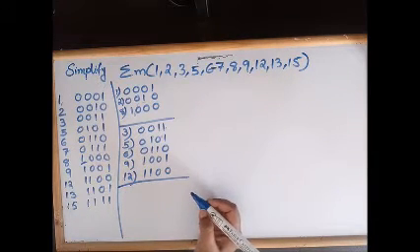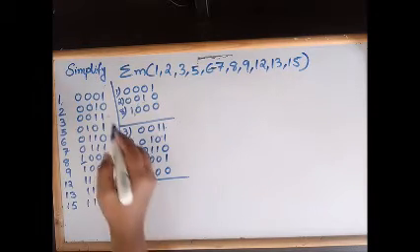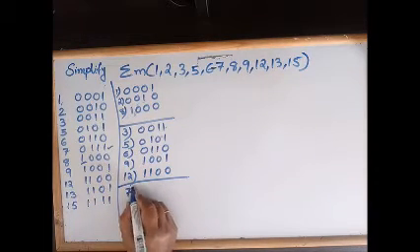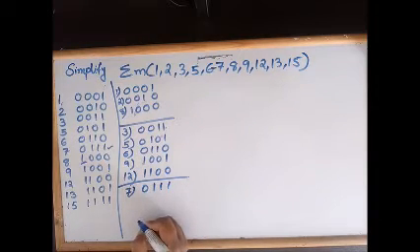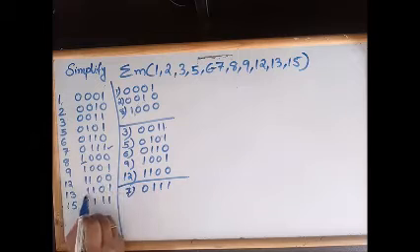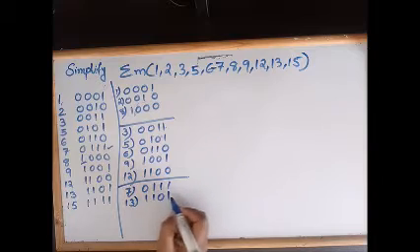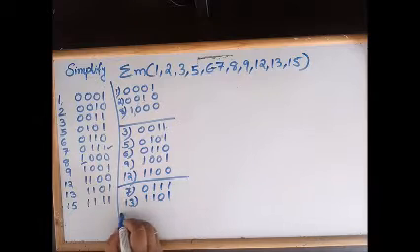Now we can generate the third group. This third group means the group of min terms which is having 3 ones in that binary representation. Okay, so consider the 3 one bits. When you consider the 7, it is having 3 ones in the binary representation, that is 0 1 1 1, 3 ones, right? Then any other number? 13. So 13 is 1 1 0 1, which is again 3 ones in the binary representation and no other term. So this will be the third group.